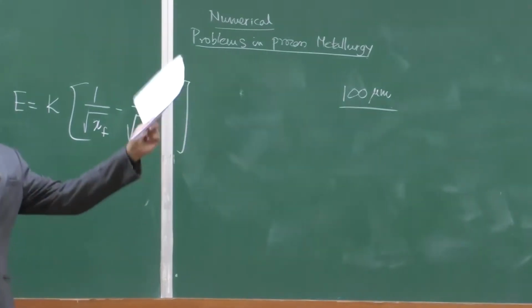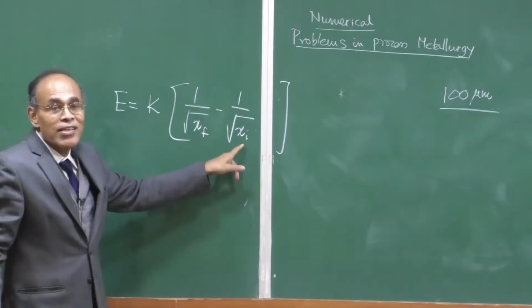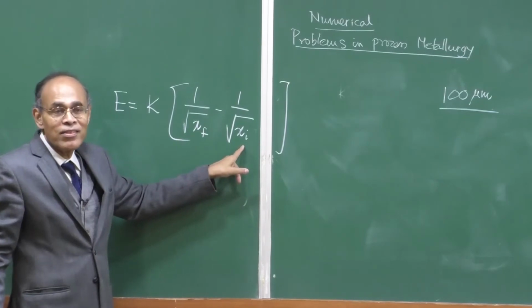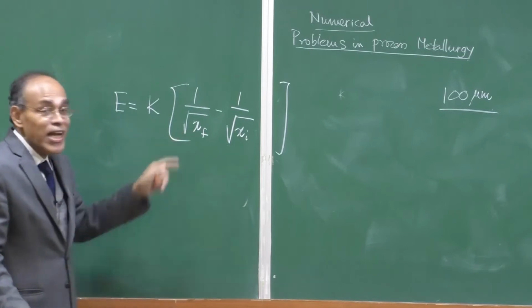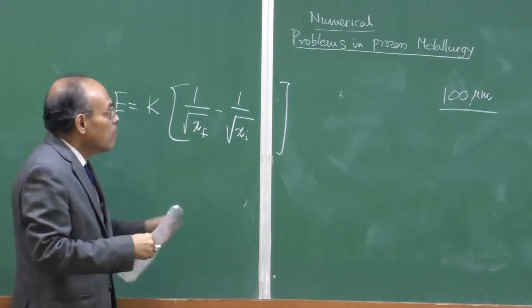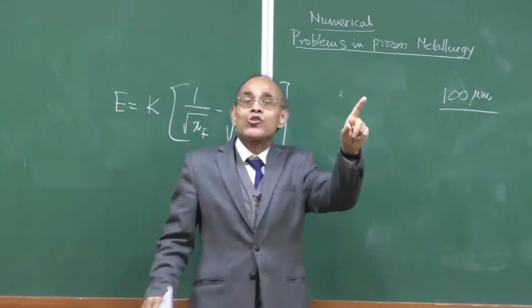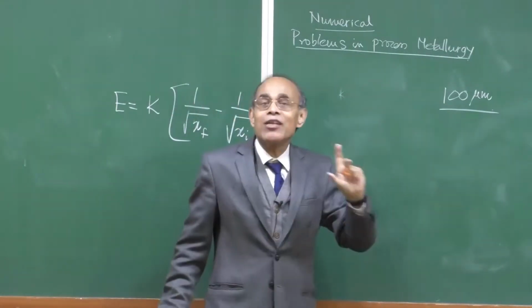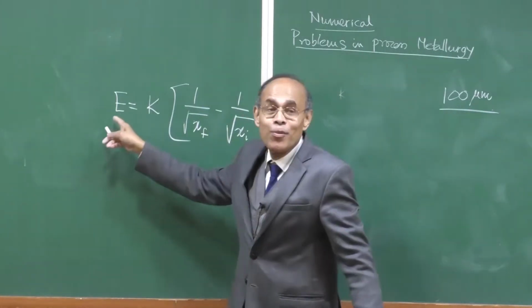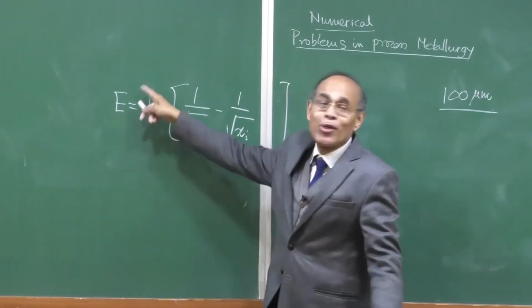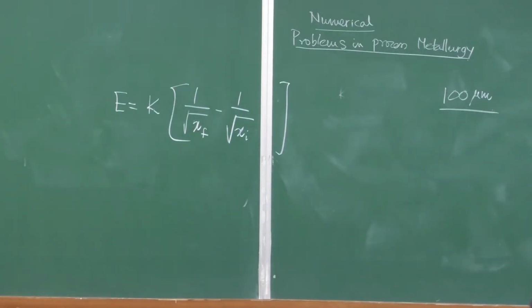So, you have taken a very big size. The moment you take a very big size, this term becomes equal to 0. Initial size is infinity, and the final product requirement is that 80% of it should pass through a 100 micron size screen. In that case, if you experimentally determine E, you should be able to find out the K parameter for that ore for that particular machine.